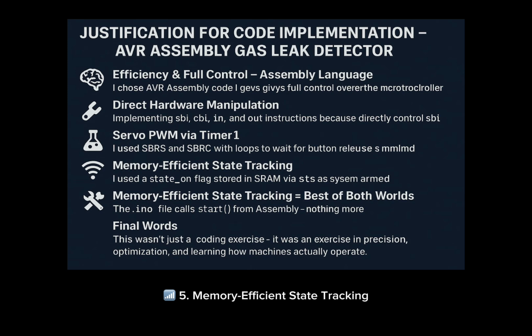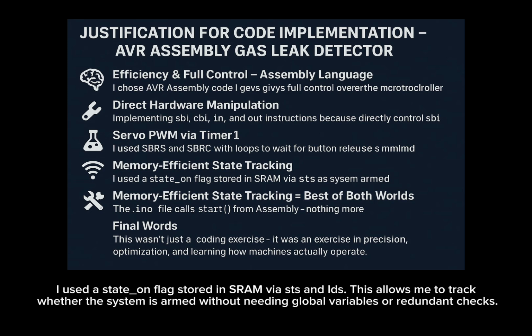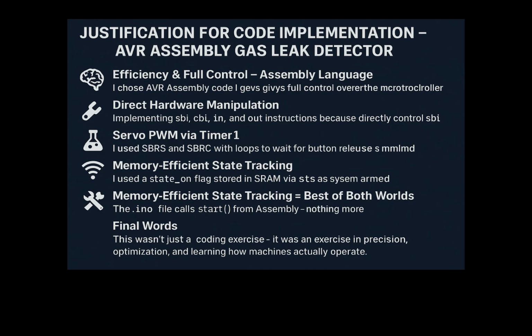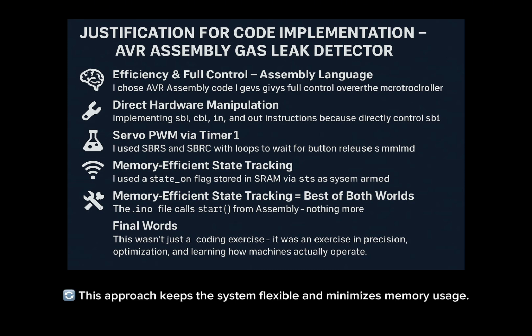5. Memory efficient state tracking. I used a state underscore on flag stored in SRAM via STS and LDS. This allows me to track whether the system is armed without needing global variables or redundant checks. This approach keeps the system flexible and minimizes memory usage.